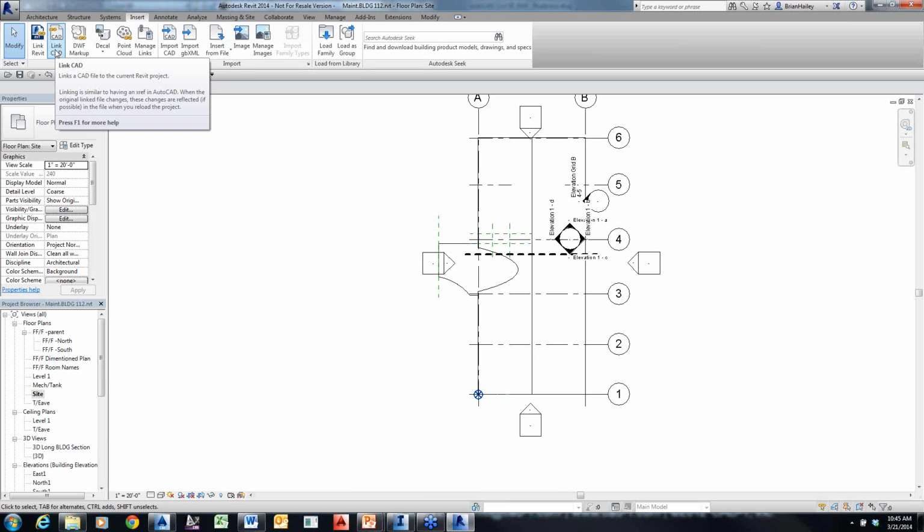Now, I do want to talk a little bit about the differences between how Revit creates a surface and the way Civil 3D creates a surface. Oh yes, in Civil 3D, we create our TIN models all the time. It works great. Revit does not look at the triangles. It does not look at the break lines. All it looks at is the points.